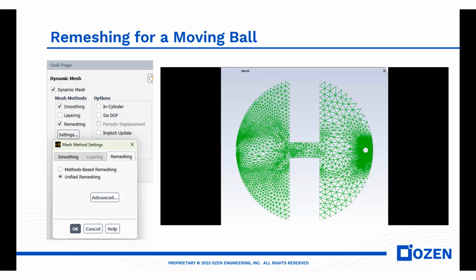Hopefully I could show you the main steps for setting up dynamic mesh motion. You need to think ahead about the moving walls, about where the moving mesh is in contact with other boundaries or zones, and whether these zones are deforming or can be stationary type.